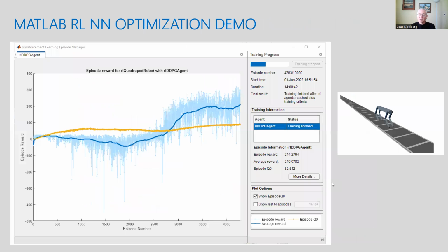During the training process, what we see over here, again in MATLAB with a particular agent, DDPG, and what we'll see when we run it, is the motion of the robot when it falls down and gets up and tries again and again and again in the episode. And we see that over here we've seen 4,000 episodes. Now, unlike PID, where you can tune the machine with 3 parameters right on the machine itself without destroying it, it would not make sense to train the machine 4,000 times. It is time consuming, and every time it falls, it may actually be damaged.